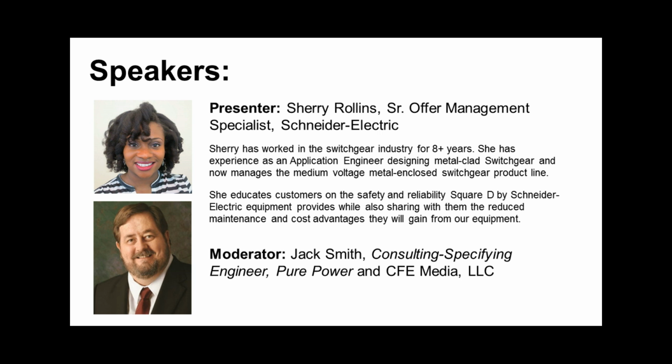The next question: are fixed breakers electrically operated, and do you need a DC battery or DC bus for controlling? Yeah, since they're going to meet the same ANSI standards, and if you have the UL listings, the control power requirements will be the same. There's nothing about fixed gear versus withdrawable gear that's going to create new control power requirements. So whether you're using DC control power with batteries or AC control power provided by the end user somewhere, those would be the exact same criteria.